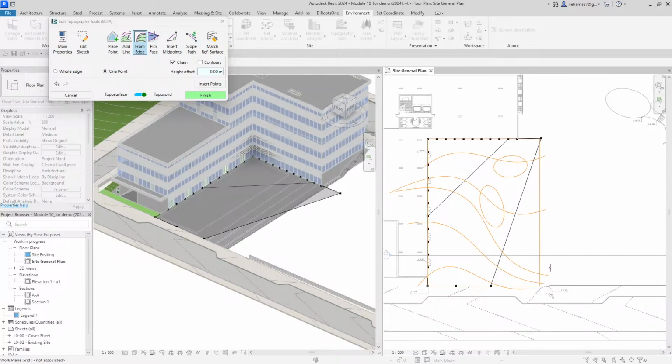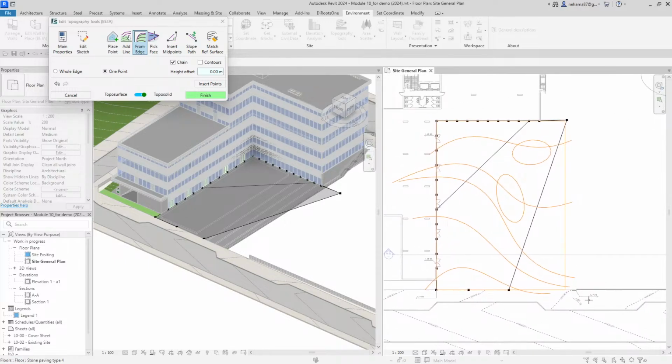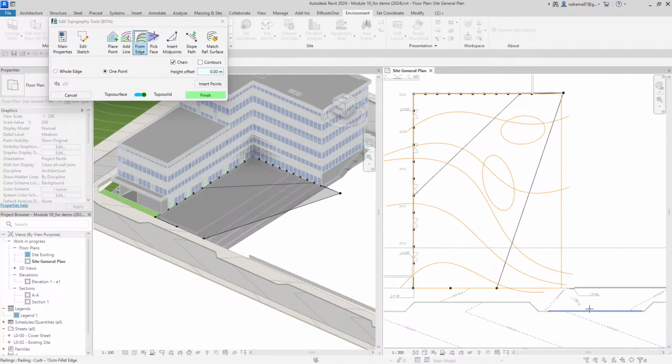All right, so next, what I want to do, it's not enough for me that my surface is connecting the building into the street. I also want to send all the water in a specific direction. And the strongest tool for landscape architects or for site designers to do that is by just using slopes.